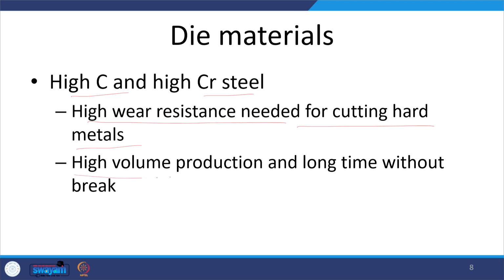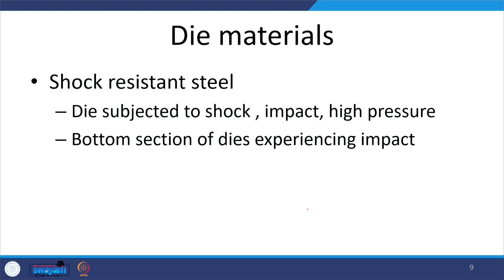So, these are preferred when high volume production is needed and we expect long life without break. Without break means without any failure tendency or requirement of repair during production. So, high chromium and high carbon steels offer long life. Long life will allow continuous operation without a break.